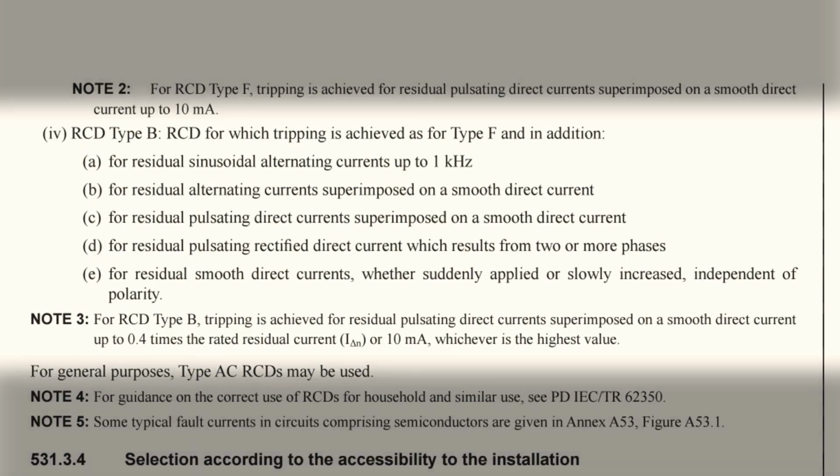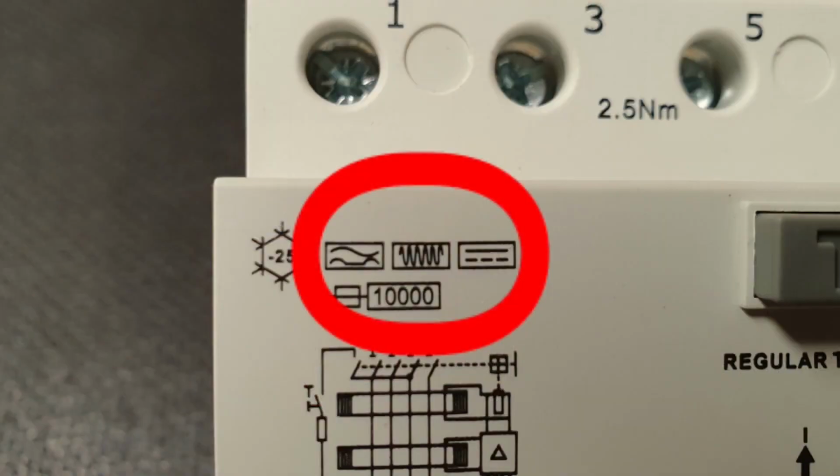So clearly then, this device is a much more complex piece of kit, and this is reflected in the types of load that it can protect. Things like lifts, escalators, PV installations, welding equipment, inverters, and uninterruptible power supplies. They also may be used in connection with EV charge points. If an EV charger requires RCD protection, an RCD Type B is one option that can be used. RCD Type Bs can be identified by this symbol.